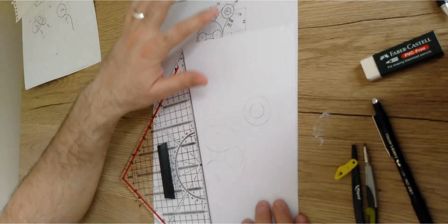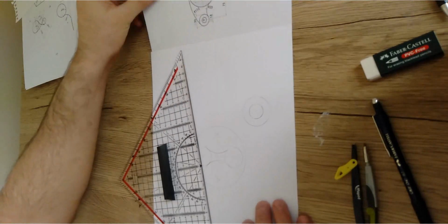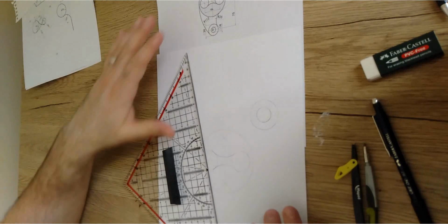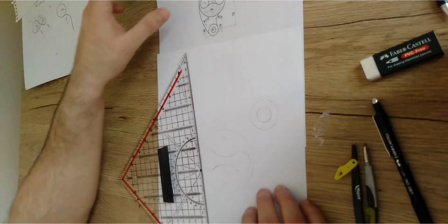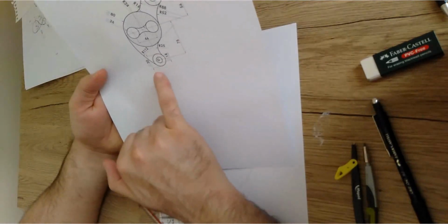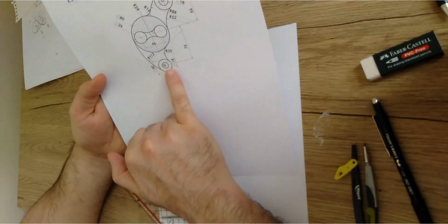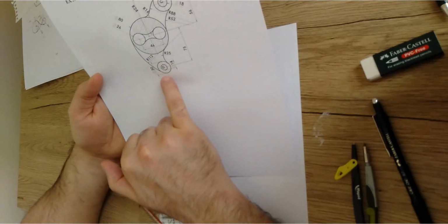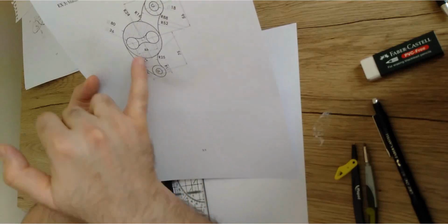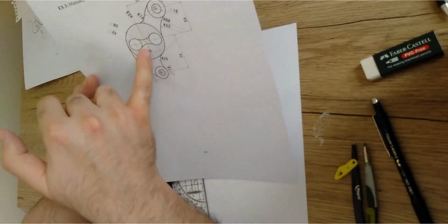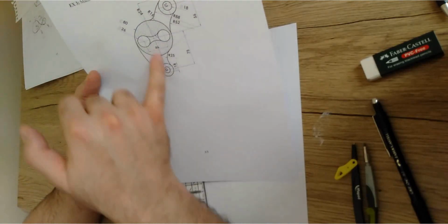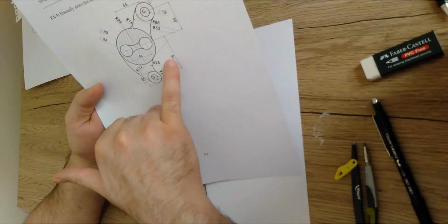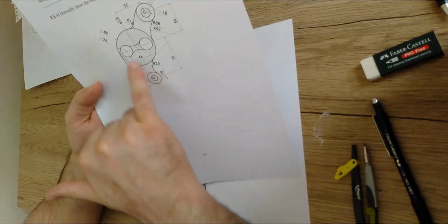Skip these curves on the top here and let us work on the other circle down here. Then we're going to finish all the circles, all of them together. This circle, the big one has a diameter of 30, the small one a diameter of 14. But this circle's center point is already located over the center line here, this vertical center line, right? So what does it mean? And it is at 57 millimeter from this center point.